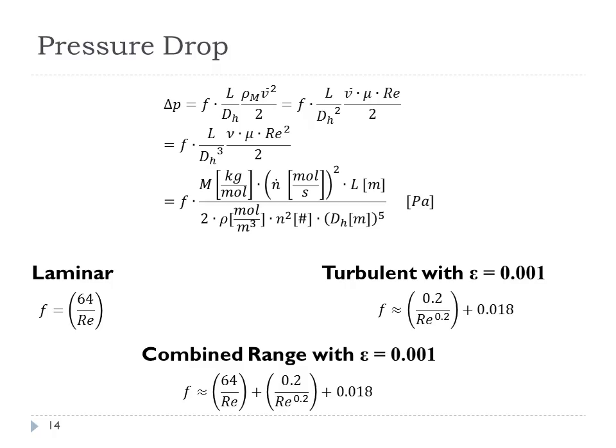So the last thing we're going to be doing in this lecture is looking at the pressure drop. We're going to need to know the pressure drop because if we were to make the heat exchanger larger and larger, we would find that the pressure drop would continue to increase. If we make the length of the heat exchanger longer and longer, the pressure drop would increase. And we have to somehow pay for this pressure drop. Pressure drops don't come for free. It typically means that you have some compressor you're going to have to run hard, more power, and hence less power from your power plant.